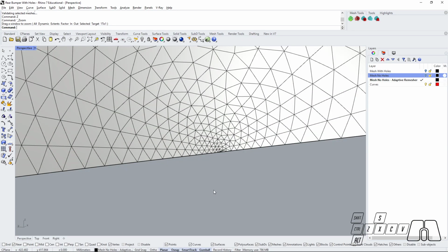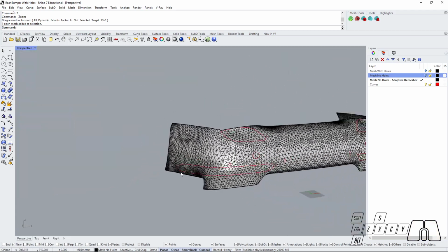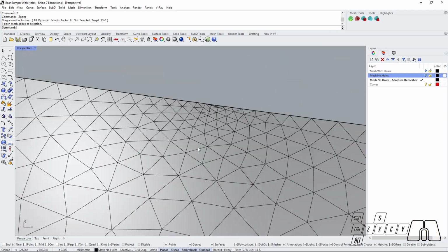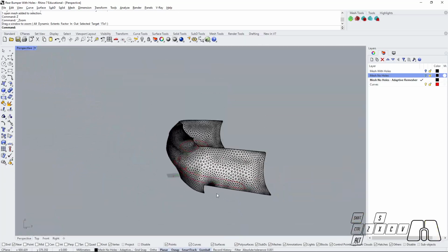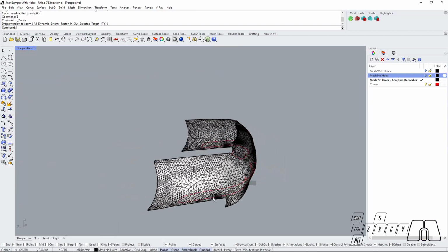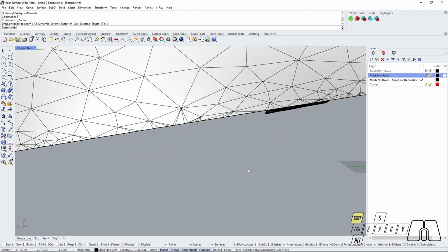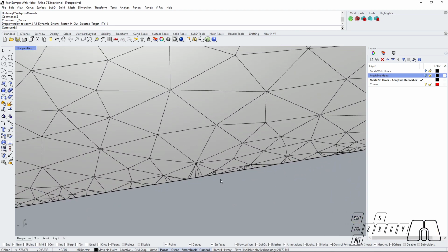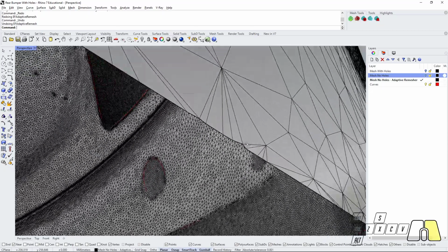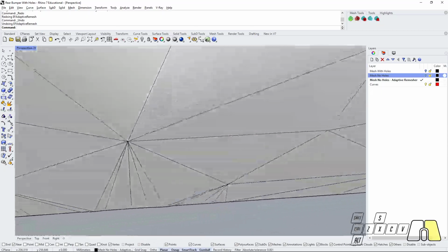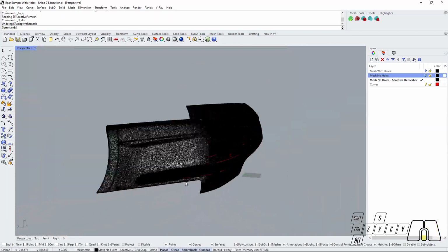So here we can see that we got a potential issue here, and that's because, well, the polygons will concentrate in that area, and here we had other potential issues as well. So these issues will come from the original file that we had, and we can clean that up either in VX model again, or we can clean it up here. So I have to see why this happened. Well, there's probably a small geometry issue.